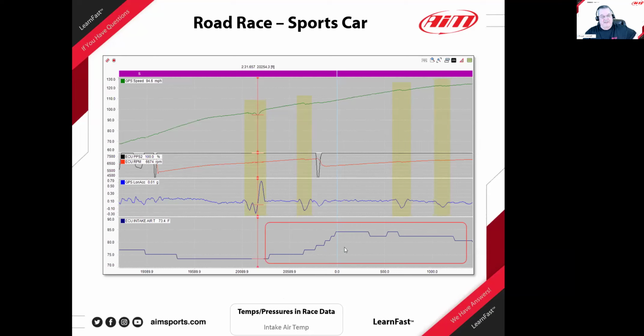But one of the cool things about an intake temperature sensor is that it's picking up the air through the front of the car, obviously. So I brought up the intake temperature, and this is now something that I bring up to understand runs down the long straightaways in this class a lot. The air temperature is bumping along here, 72, 73 degrees, 73.4, right where I put the cursor when he first started to catch the car in front of him. And then look at the temperature rise up, and eventually all the way up to almost 85, probably 84 degrees. So a 10-degree swing in temperature over a very short period of time, as he got pulled right in behind somebody and was bump drafting him up the straightaway.